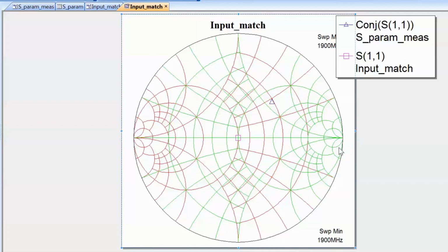However, because we are working at a relatively high frequency, which means that our wavelength is relatively small, it is advantageous in this case to use transmission line matching. And it is also very instructive for you to understand how it is done in a practical case. And there are a couple of tricks which I'd like to show you. Implementing an L-section matching with transmission lines entails using shunt stubs, and these can be either open-circuited or short-circuited. In this case, let's use open-circuited stubs to begin with.